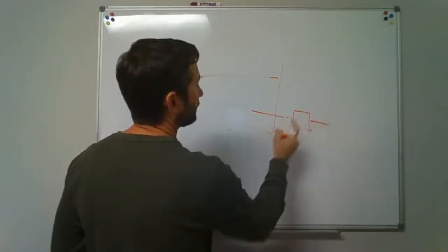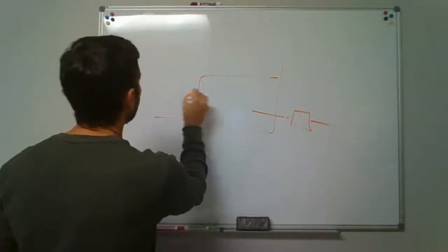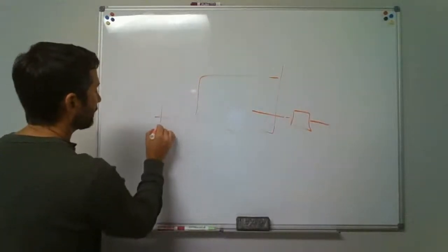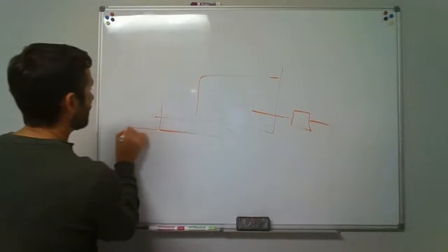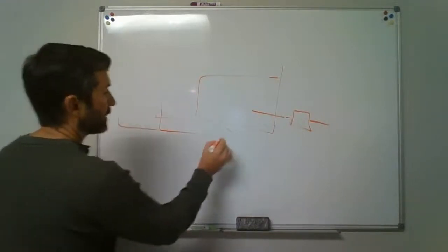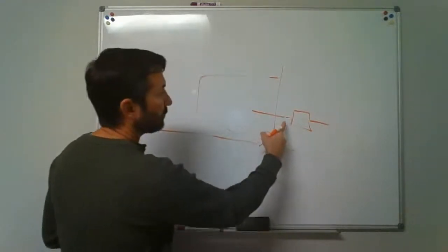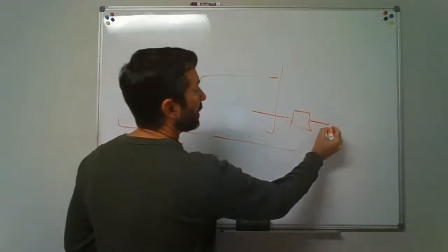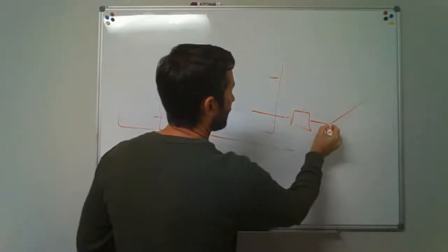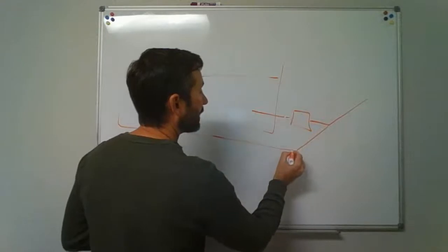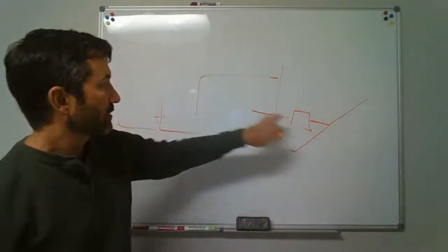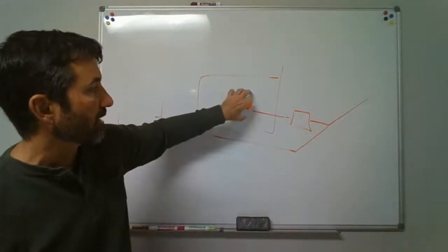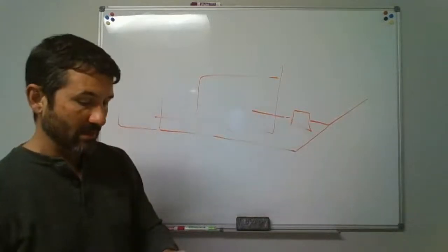So this was the inlet that was treated. We had men's and women's bathrooms, and we popped that through, and that ran down, and came up, and maybe went in and caught another bathroom, came down along this, but we didn't connect the two in here. On the outlet, as that went down, we came in beyond that area and passed it too. So only what needed treatment through that kitchen area was coming through that interceptor.